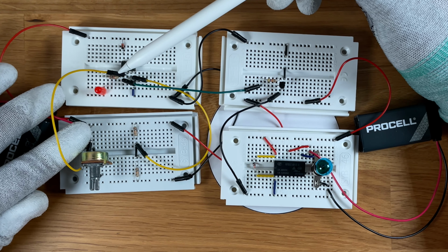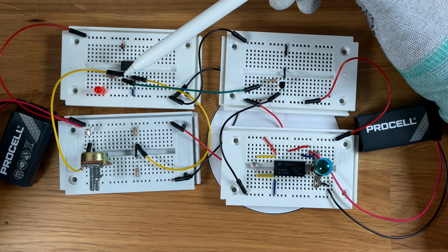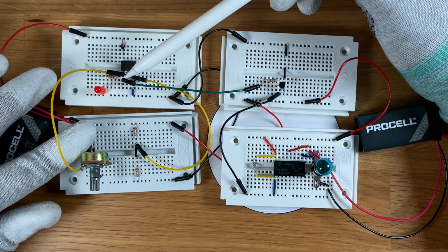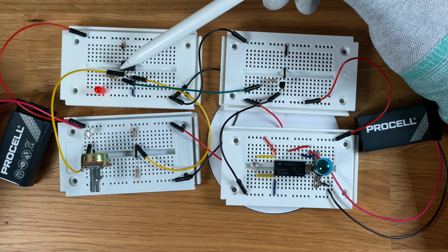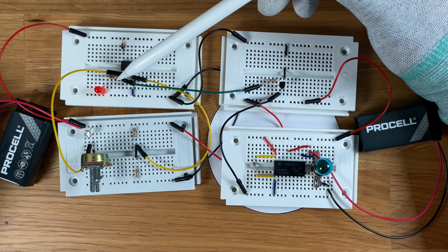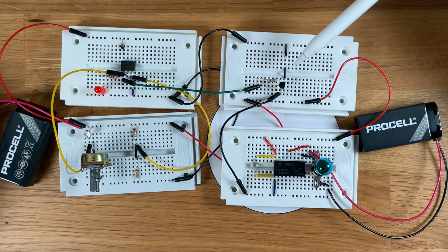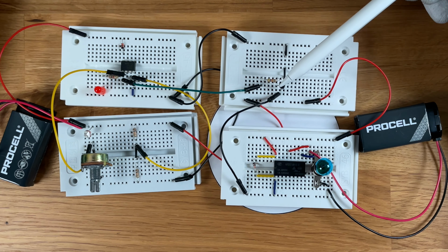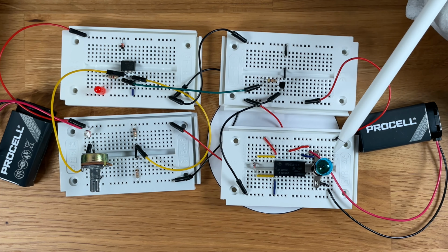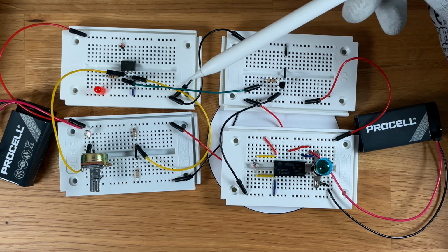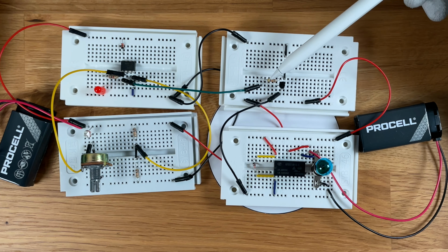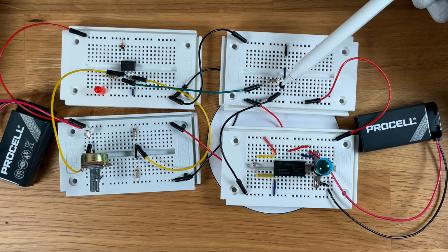And as soon as the light difference becomes positive, which happens when I block out the light, this LED will shine. Also, this voltage level at the output of the operational amplifier is transmitted to the third component in our circuit, the transistor, which we previously used to light up an LED, and which we now use to trigger a relay connected to an incandescent lamp. This green cable comes from the output of the operational amplifier and leads to the input resistor of the transistor.